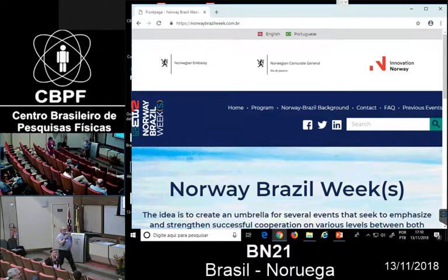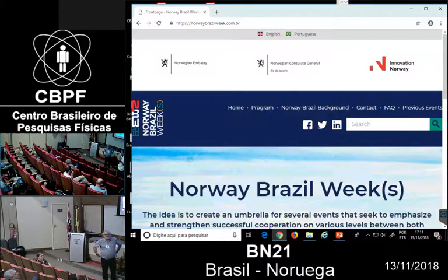Okay, to left, quick one. Quickie. Sales gas is max 3% CO2, and you said you have 40% CO2 in your produced gas. You could use membranes and reintroduce it as CO2 into the reservoirs for enhanced oil recovery. But you could use membranes, not this amine, because that is a chemical. It's not sustainable. You have to watch that sustainability. Adding chemicals, why do that when you have the membranes?